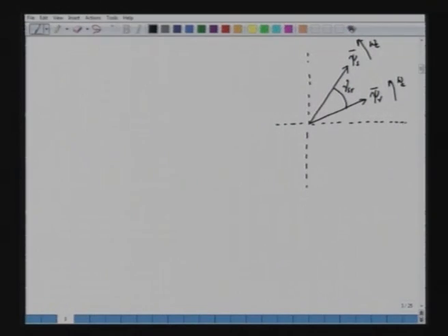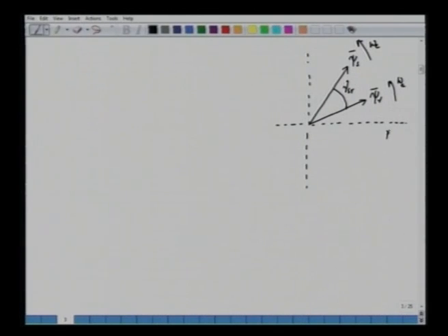And if we take a stationary axis, I can call this my phase A axis, this is also my D axis, and this axis which is at right angle to this is the Q axis. And I can find out the components of these fluxes on these two axes.